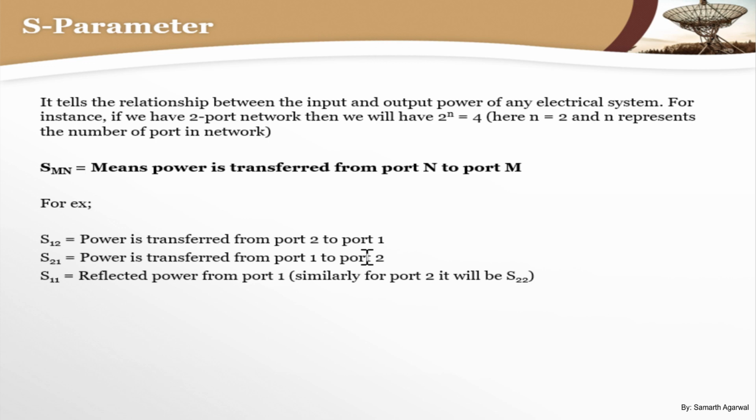Please note that since an antenna is a one port device, when I discuss the antenna results in the seventh module, that is the implementation module, we will be focusing on S11 only. But in the case of a MIMO antenna, which is multiple input and multiple output, as the name suggests, it will have different ports. So we will look at S11, S12, S13, S14 in the case of a 4 port MIMO antenna.